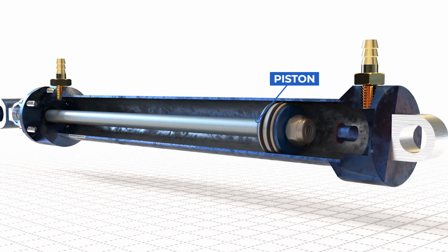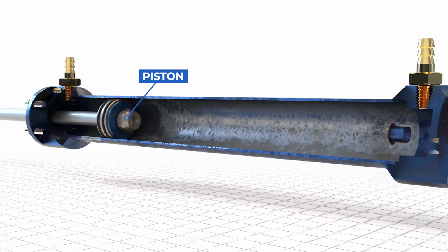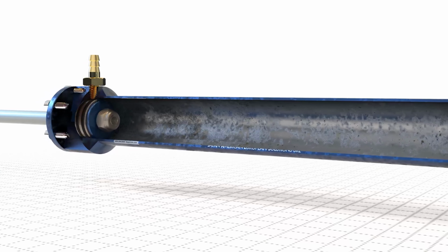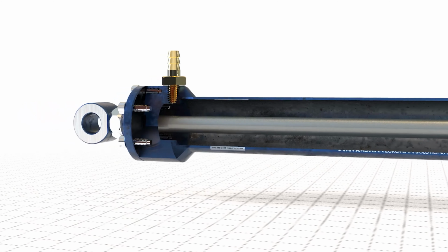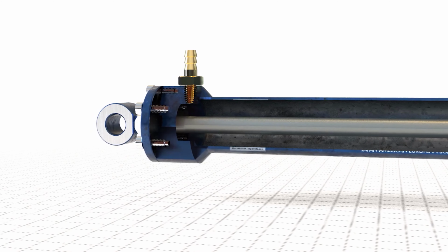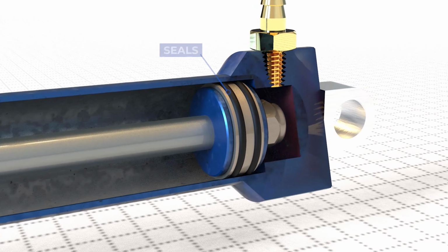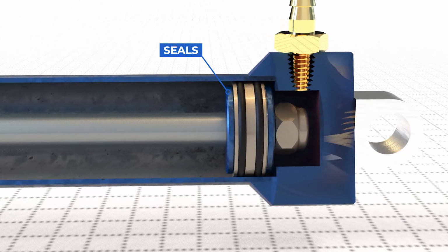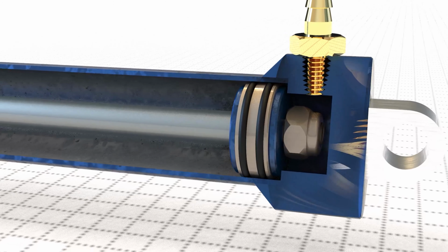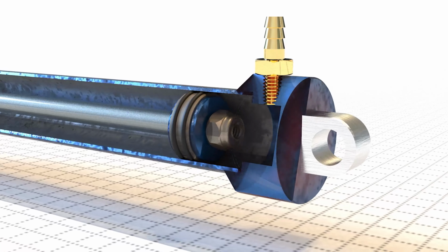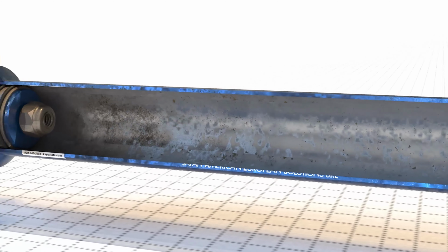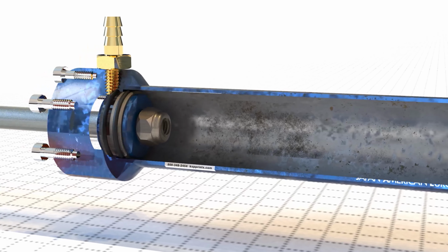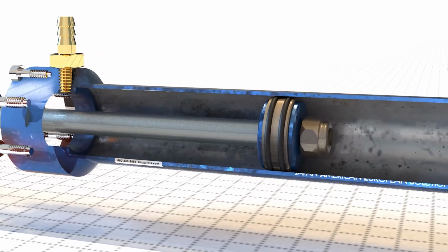A piston is attached to the piston rod. It splits the cylinder bore into two compartments and reciprocates back and forth when the pressure is developed on both sides of the cylinder chamber. A set of circular sealing rings are used in the interface of metals. The seals used between the surface of the metals in relative motion are dynamic seals, and those acting between two surfaces at rest with respect to each other are static seals.